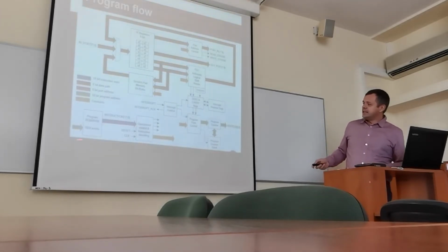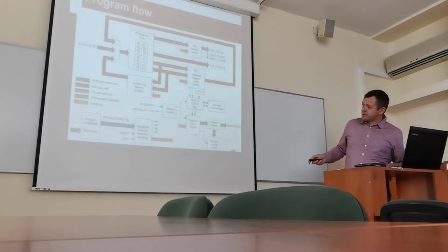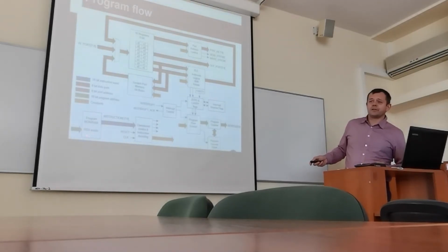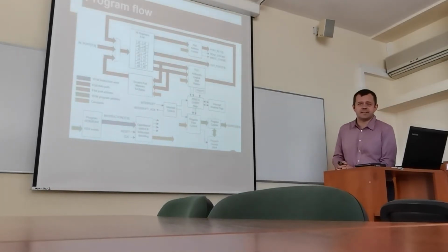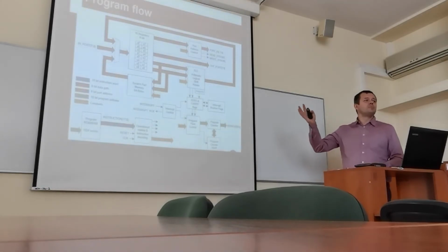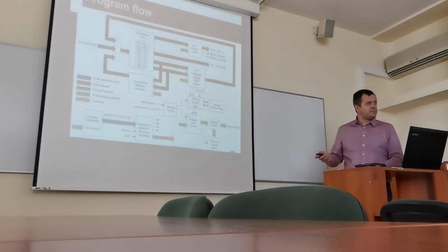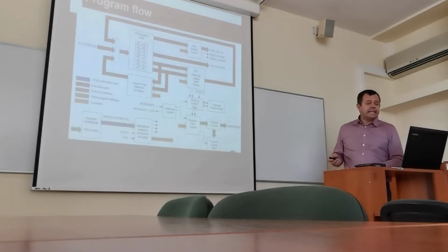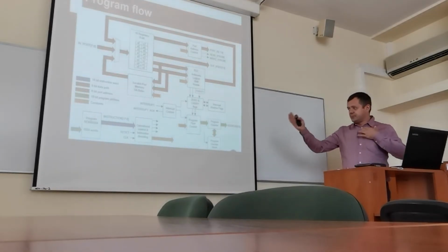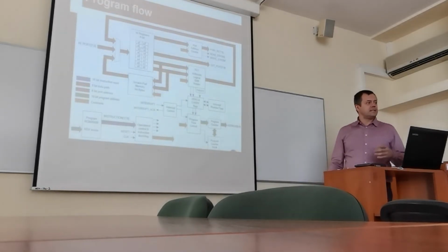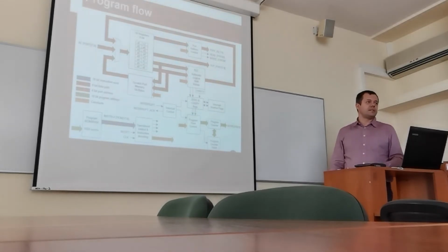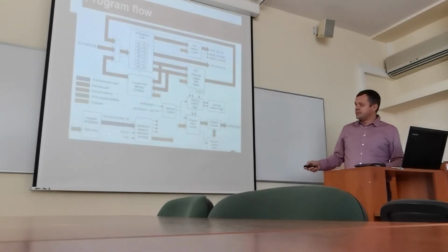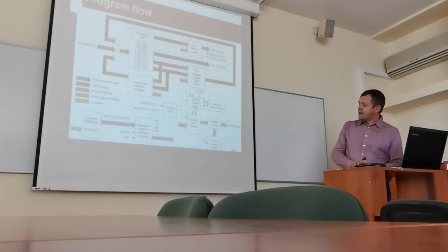Here in this microcontroller, a word is 18-bit. So the memory is not 1000 kilobytes, but about 2.3 kilobytes, because you multiply 1024 by 18 and divide by 8 to get kilobytes. But the most important is 1024 words.